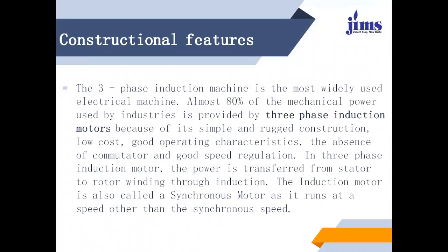In AC machines, there are two types: one is the single phase machine and the other is the three phase machine. Here we are discussing the three phase induction machine, which is the most commonly used in electrical applications. Almost 80% of the mechanical power used by industry is provided by the three phase induction motor, because of its simplicity and rugged construction, low cost, good operating characteristics, the absence of a commutator, and good speed regulation.